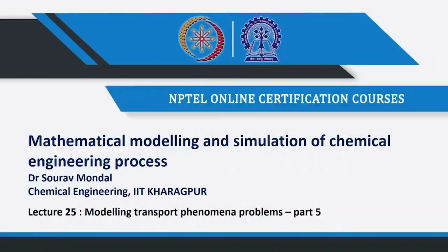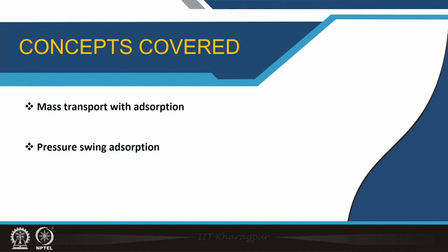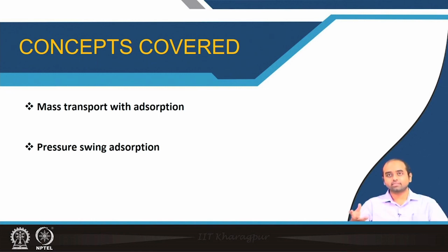And the key technology behind this oxygen concentrator is the adsorption process. What essentially happens here is the adsorption of nitrogen into molecular sieves, which results in further enhancement in the oxygen fraction in the produced air.